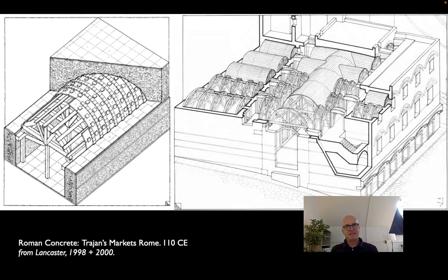That is not the ideal structural shape. We know today that a catenary, a shape that's more like a parabola, is more efficient and more effective at carrying loads. Romans wouldn't have known that, and it's very difficult to both lay out and to build a parabolic shape out of timber, out of the materials that Romans had. And the semicircular shape is a sort of perfect balance between the ideal performance shape and something that's relatively easy to build, right, within their abilities in terms of kind of drafting, but also in terms of fabricating on the ground.